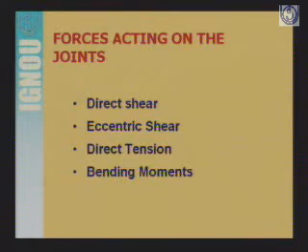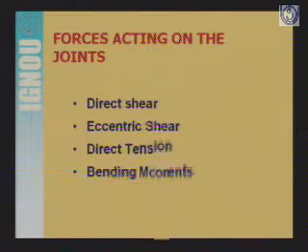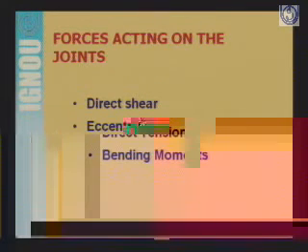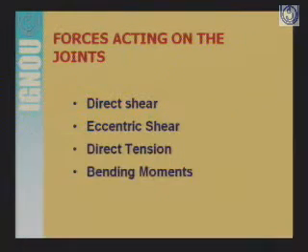When an eccentric load is acting on the connection, there will be two things: direct shear will be there, as well as moment. Because of the load multiplied by the eccentricity, that moment will also come into the picture at such connections. So these are the forces that act on the joints.